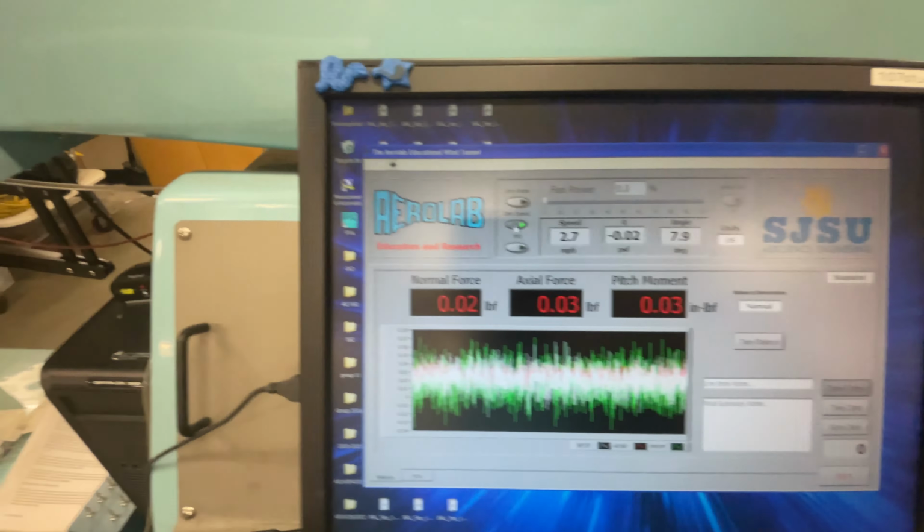This is a wind tunnel that uses air, so we can always assume that we're dealing with air. Temperature, we have this sort of convenient ultrasonic bath over here that reads out the temperature for us. So we can see that this is 22 degrees Celsius right now. You can read off your own value once you come into the lab and get an updated value for that. For most groups, it's going to be between about 22 and 24 degrees Celsius, based on the weather we've been having the last couple weeks.